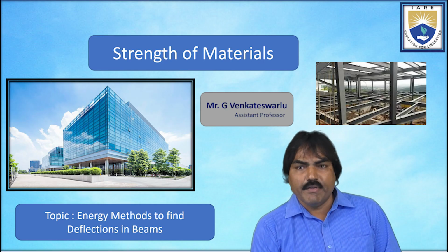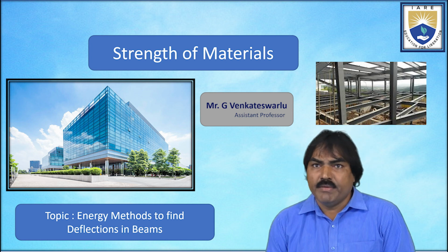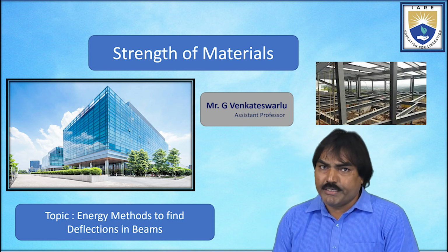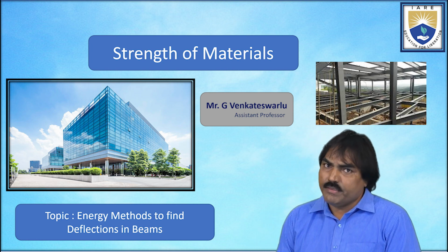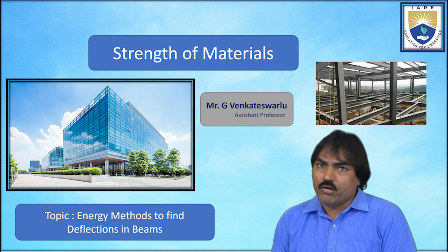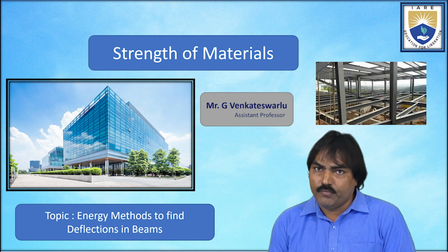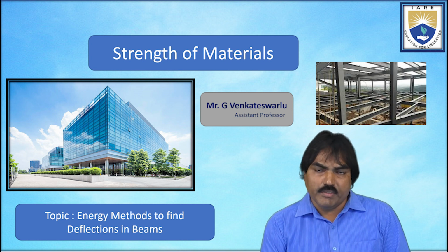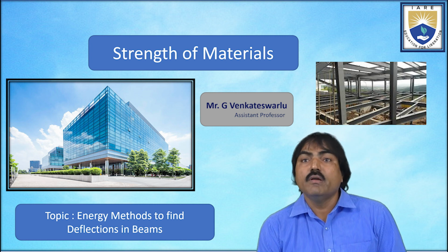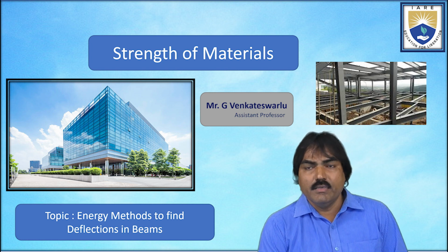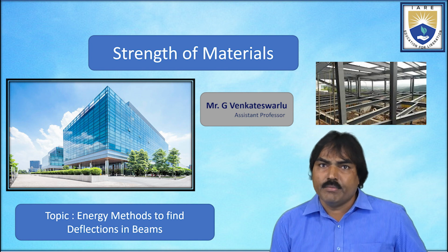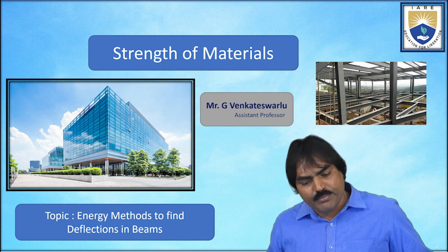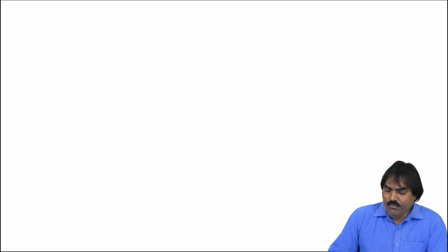Energy methods to find deflections in beams. Deflections can be determined by so many methods like the double integration method, energy methods, area moment methods, column analogy method, even the conjugate beam method. Out of all these, energy methods are more powerful and follow a standard procedure to find the support reactions, and even the deflections and slopes in beams, for both statically determinate as well as statically indeterminate beams. So in the energy methods, when you apply load on the structure, any elastic structure,